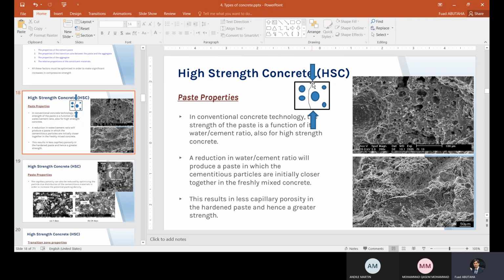When you put the sample in the machine and it fails, and you take it out and split it into two parts, you can see where the crack went. You can see that the aggregate particles are still not broken, and the crack just went through the cement paste, which in this type of concrete was the weakness part.